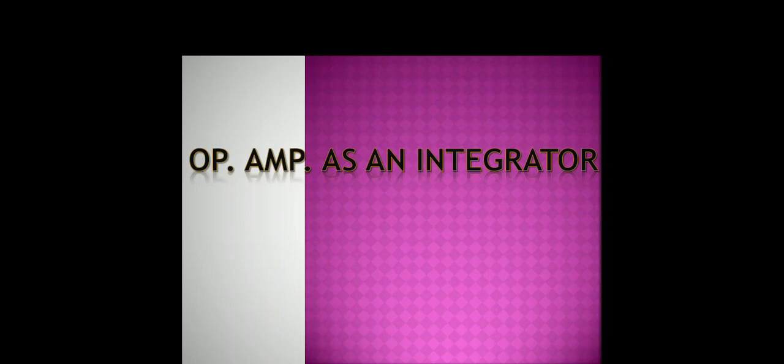Today's topic is op-amp as an integrator. An op-amp can be configured to perform calculus operations like differentiation and integration. In an integrator circuit, output is nothing but the integration of input voltage with respect to time. Op-amp differentiating and integrating circuits are inverting amplifiers with appropriately placed capacitors and resistors.